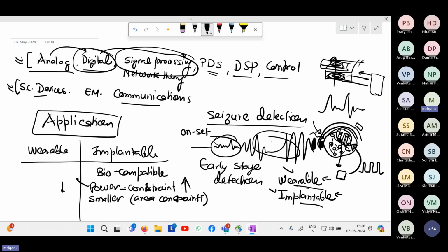Power constraint is not only because of the battery operation. There is another reason. Anybody can guess? One is the power constraint because of the battery, or basically you have to supply the power inside the chip. Outside it is anyway chargeable. Inside you have to rely on inductive coupling. In another implantable application going deep inside the body, it becomes very difficult. You can't really charge it like this. If it is near the surface, then this works. For brain implants inside the skull, it is still possible.